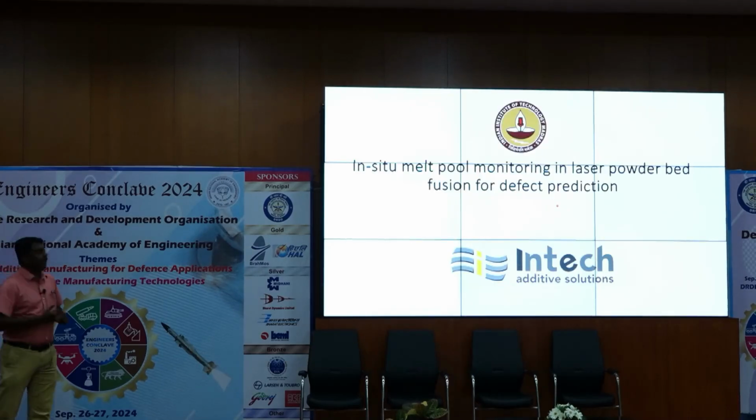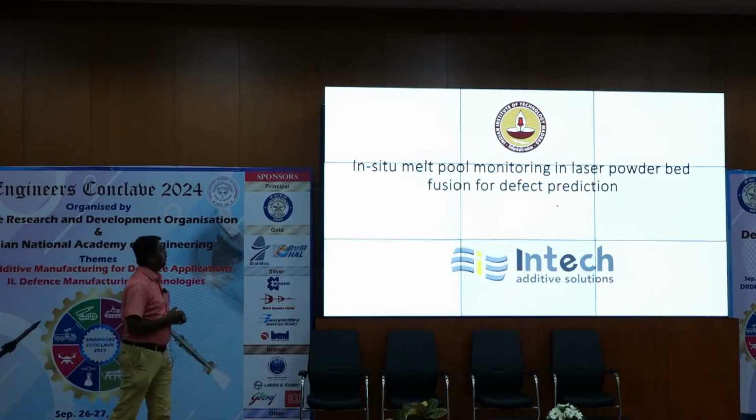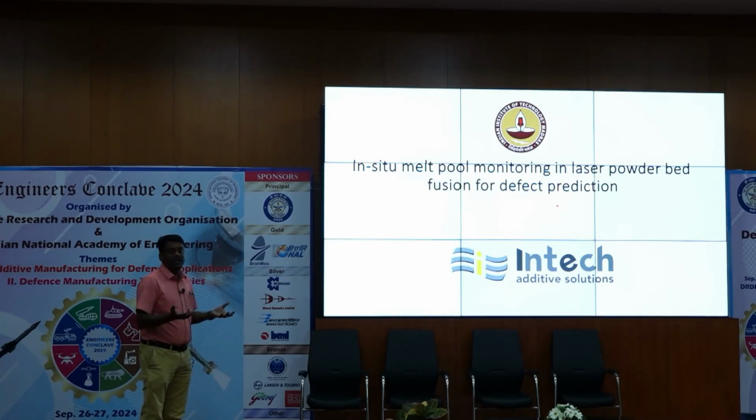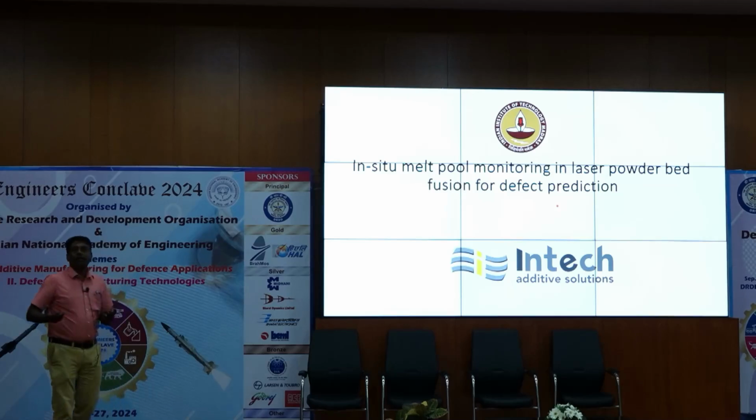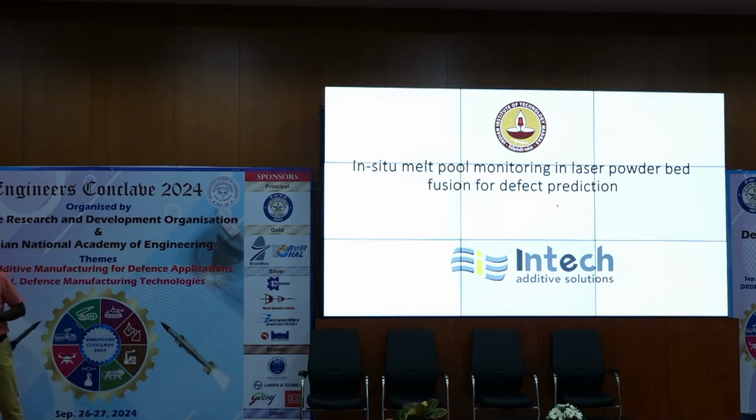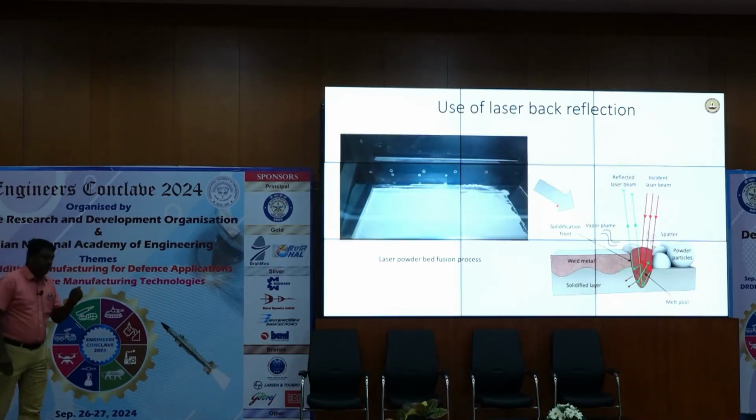Okay, the second work is on in situ melt pool monitoring. Again, the knowledge is there in welding. In welding, we have multiple melt pool monitoring systems, and we can understand from the laser reflection behavior whether a melt pool is stable, or whether it is attracting some dissolved gases to form blowholes, or whether we are also creating cracks. So a simple technique can be very effective.